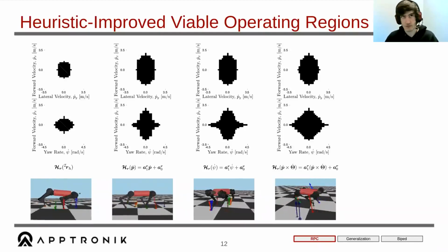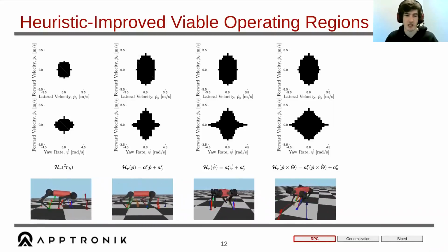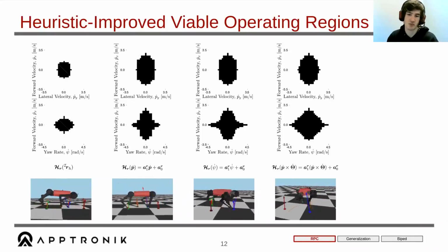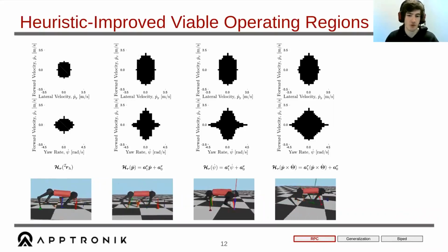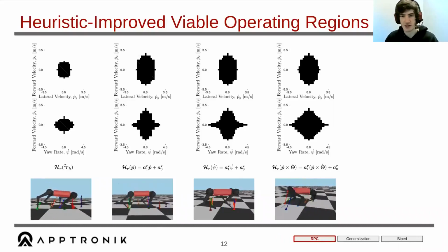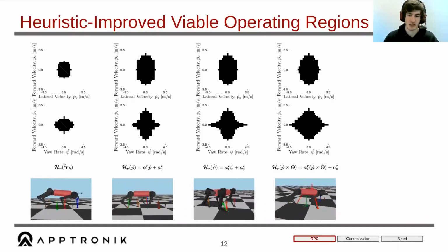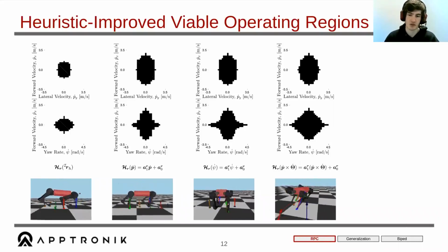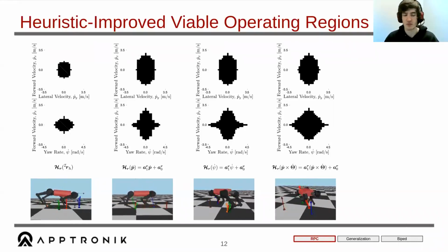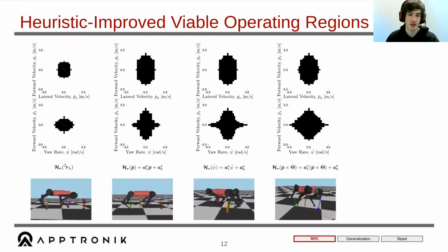The second to last one that I found was a little more interesting. It was a linear relationship on the cross product of forward velocity and turning rate. So we can see how these interactions work: as the robot's moving forward and also turning, the robot tends to put its foot outwards away from the center of the turn.